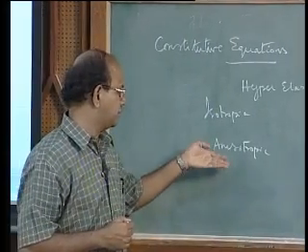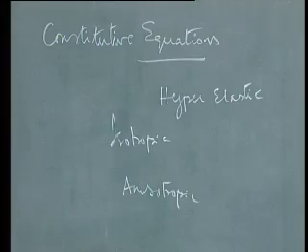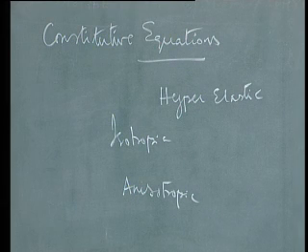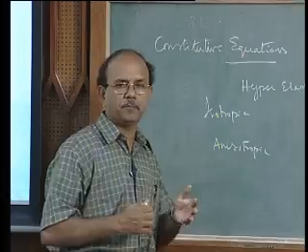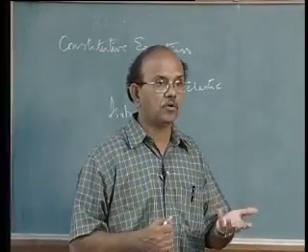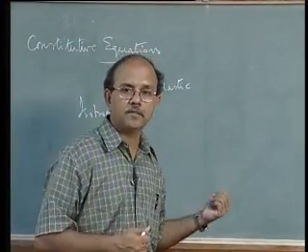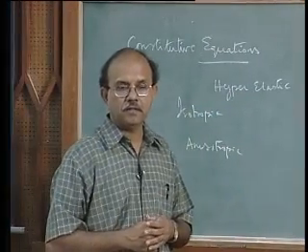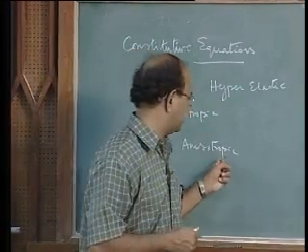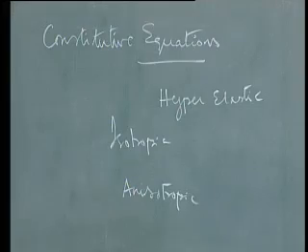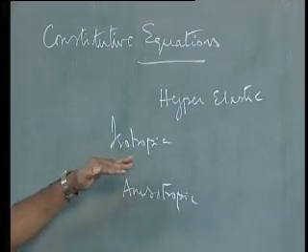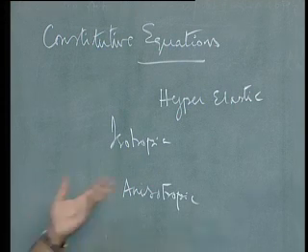Maybe towards the end, if there is time, I'll indicate how we approach the anisotropic problem. But the applications of anisotropic hyperelasticity are not very high, except biological materials. You really do not use anisotropic hyperelasticity to that extent. In fact, I'll just comment on that in a minute. Let me complete the other classification. The other one is, of course, isotropic hyperelastic materials.